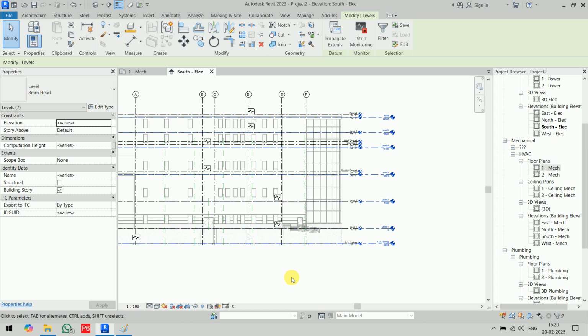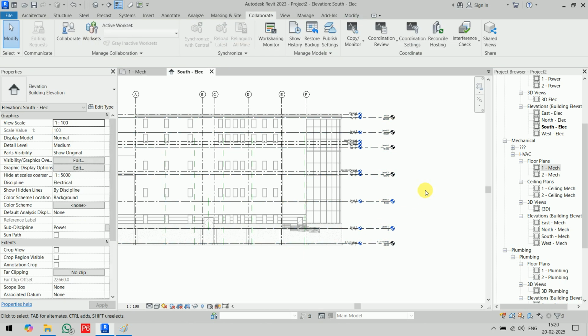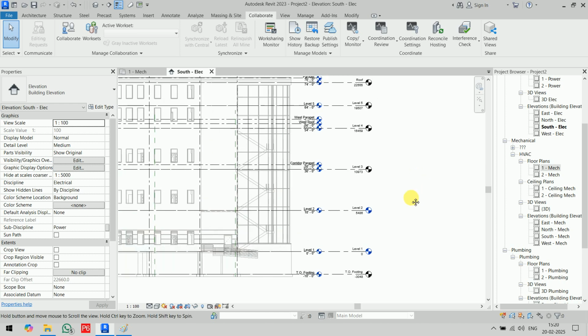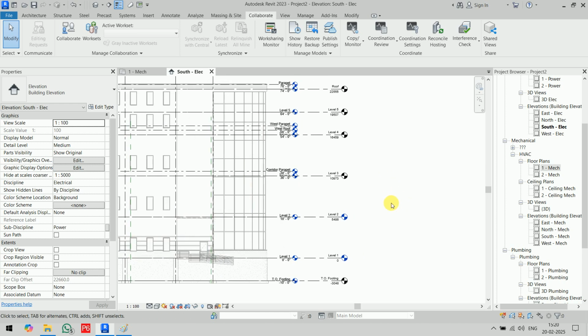And monitor means this will give you a pop-up window if there is any change in the architecture levels. Got it? This is how you can create a number of level copies from the architecture. Now you will find how it will pop up; the update depends on the architecture model. If there is any change in the architecture model, then accordingly it will pop up.